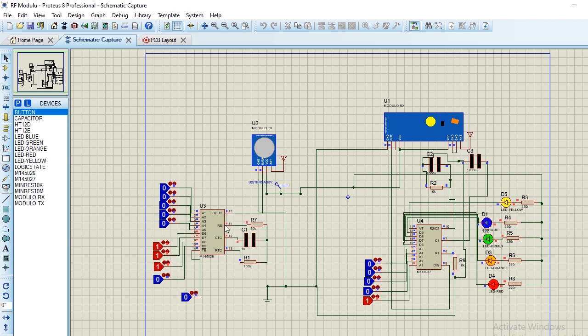So if you see, the address lines are not the same, so any information that I'm trying to send will not be received by the decoder. So in order to receive the same information, you must make sure the address line is the same. Watch, so I've turned on the address line to be the same, and you can see this is the information.